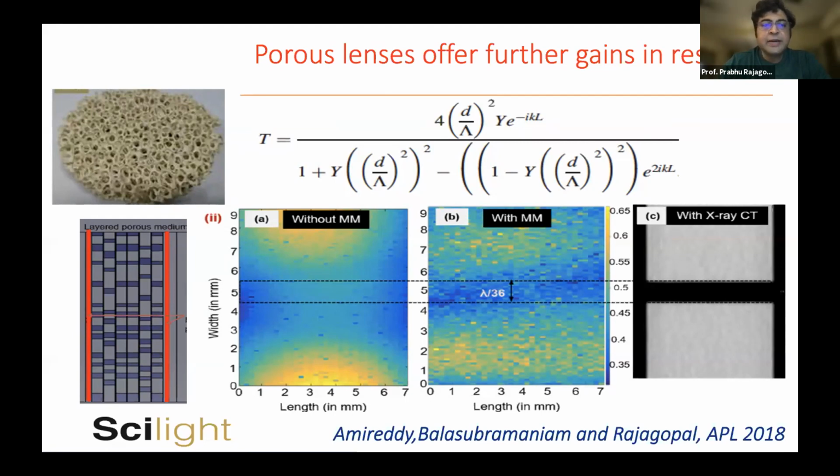So if, for example, a region is infested with cracks, surely there is something happening in terms of fatigue behavior, creep behavior that is very unusual. So not all cracks are cause for alarm, because any material will have cracks inside. But if the cracks are a lot, and if they are above a certain threshold, then there are other things to be inferred for the structure, for sure.